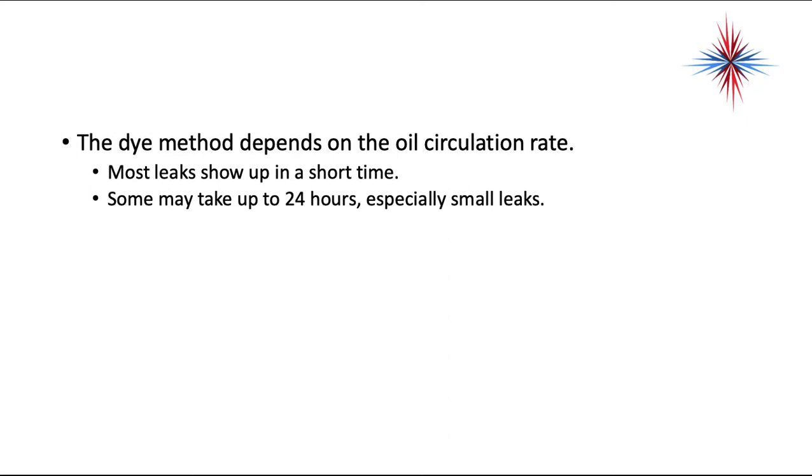So if you're using a dye, you put the dye in, return the system to normal operation, and you might have to come back to find the dye leak locations. Now, before you use dye, be very careful of this because there are some manufacturers of compressors and equipment that will void the warranty on the compressors if you use the wrong dyes or even some dyes to start with.